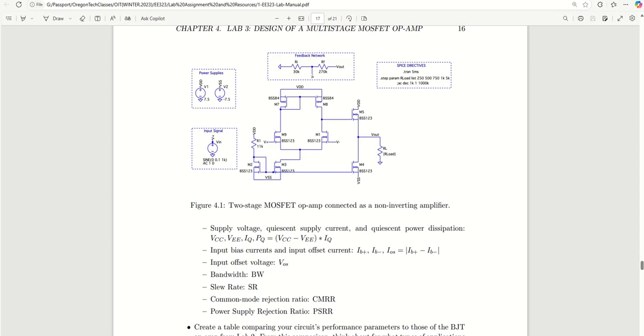The measurement of common mode rejection ratio is your amplifier's ability to reject noise. An ideal amplifier connected in normal operation should give you a very high gain, dependent on your feedback network. Common mode is when both inputs are connected to the signal. Ideally, an amplifier would see 0 on the output because they cancel each other out. But experimentally, there will be some sinusoid there, and the common mode rejection ratio is how well an amplifier rejects that noise.